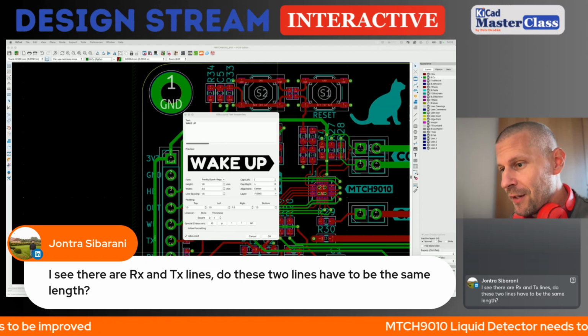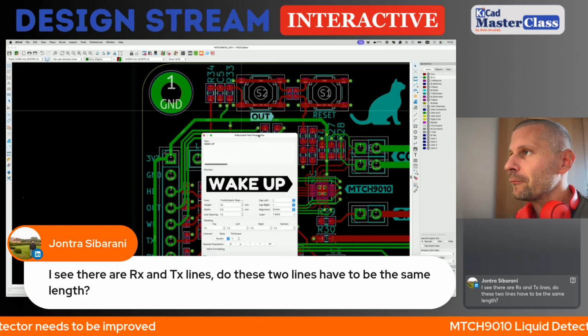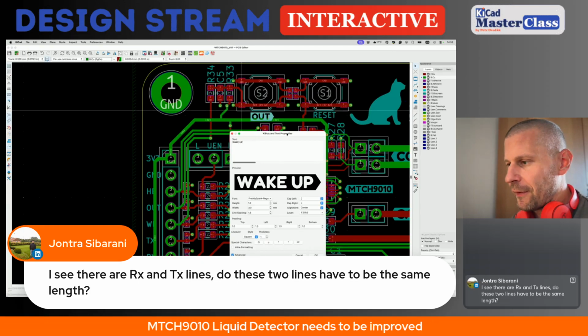Thank you. I see there are RX and TX lines. Do these two lines have to be the same length? No, no. This is the very low speed UART signal, so you don't have to bother with the length tuning.